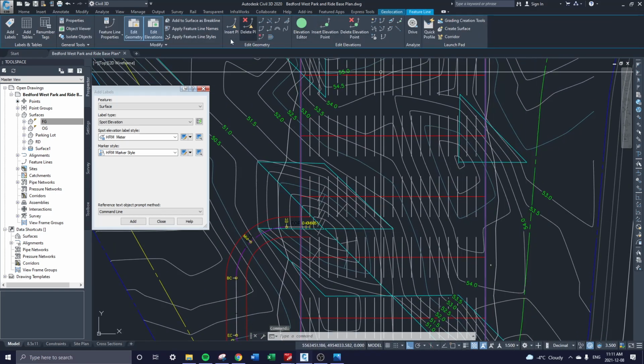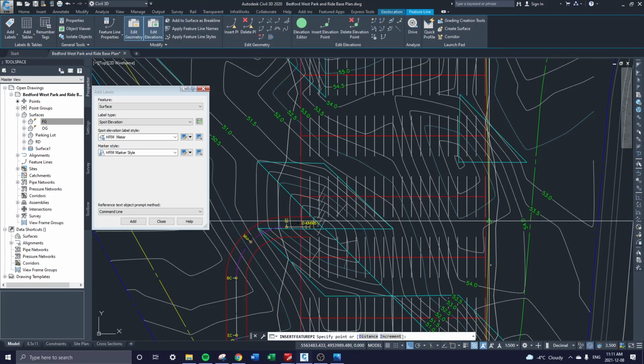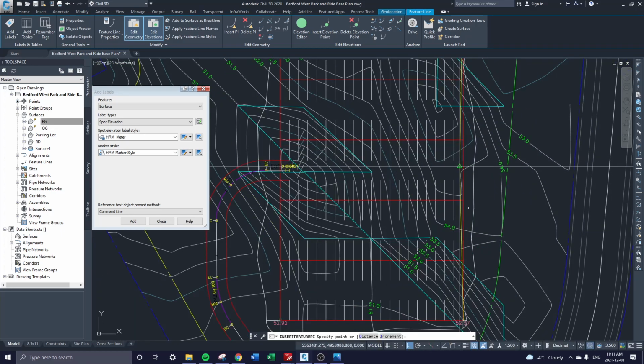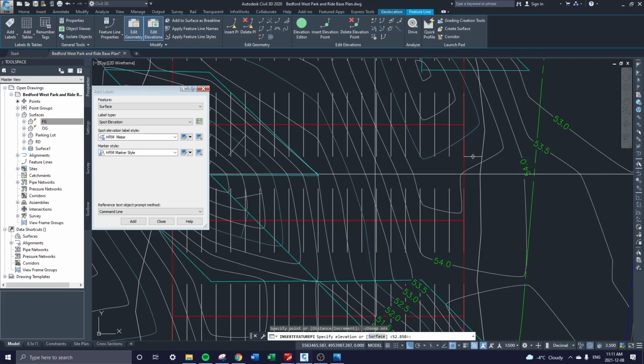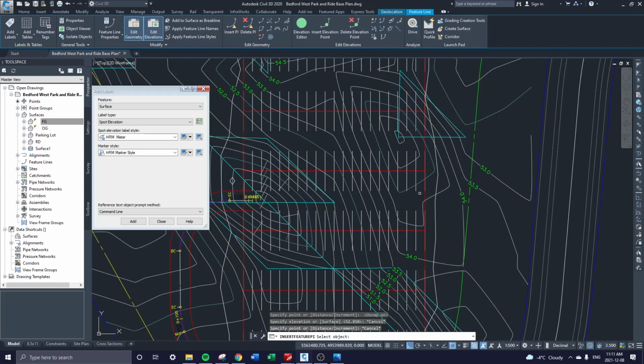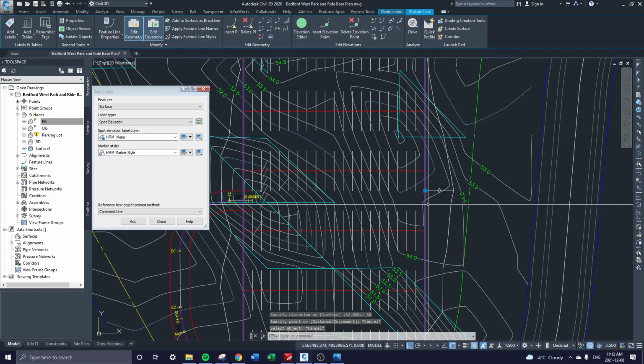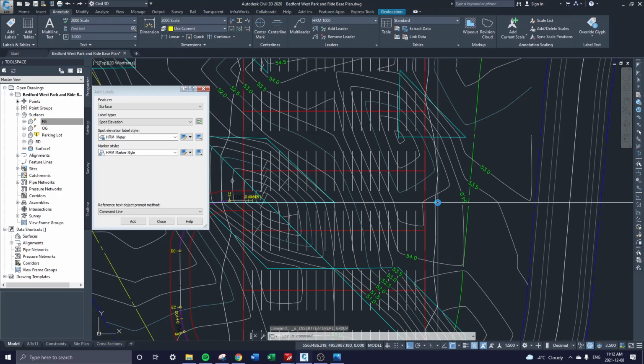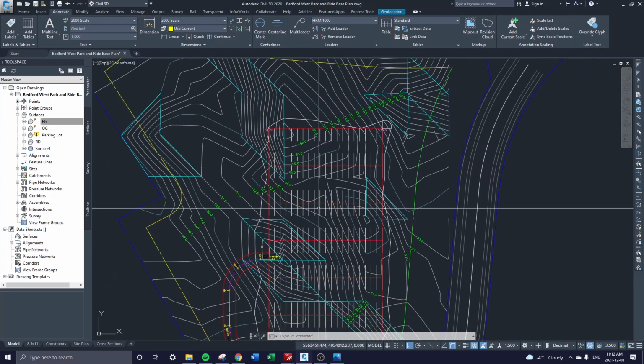You can also add PI intersections to your feature line if you wanted to. Like say maybe you're struggling with getting that cut and fill, you could add another elevation point here, right? You see how, did that add it? No, it didn't, did it? So hit there. It says down at the bottom, specify an elevation. Maybe we want that, I'll exaggerate it and say 50, right? Bam. Now there's an extra grip that we can use to kind of contort our parking lot. And that can kind of optimize your finished grade as well as your surfaces and your volumes. Okay, so that's finished grade.